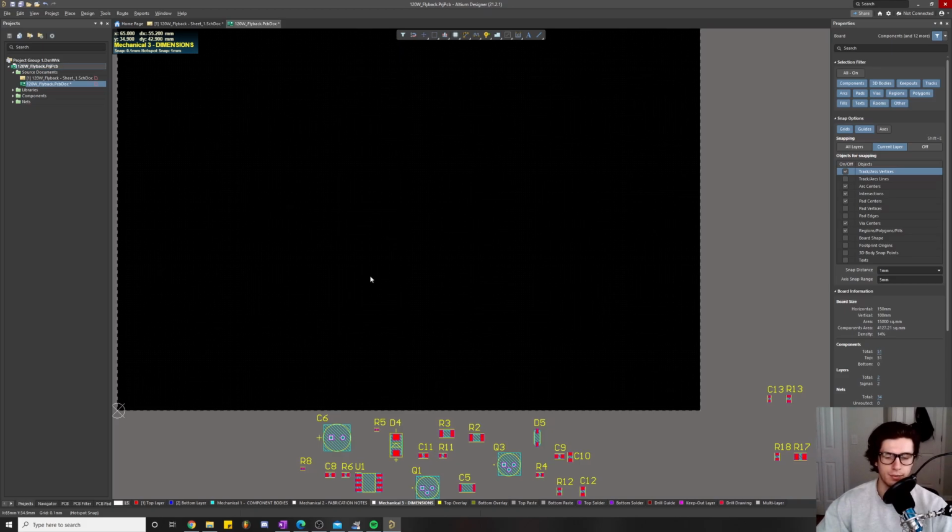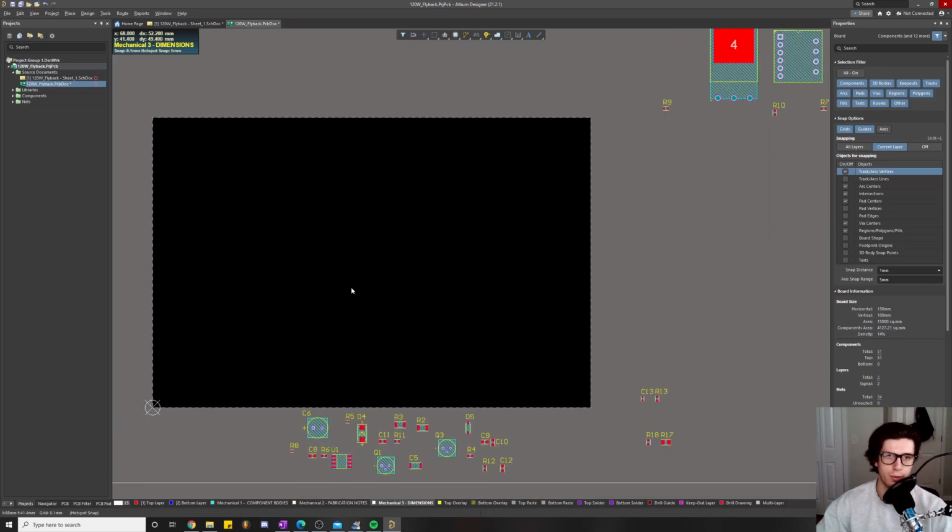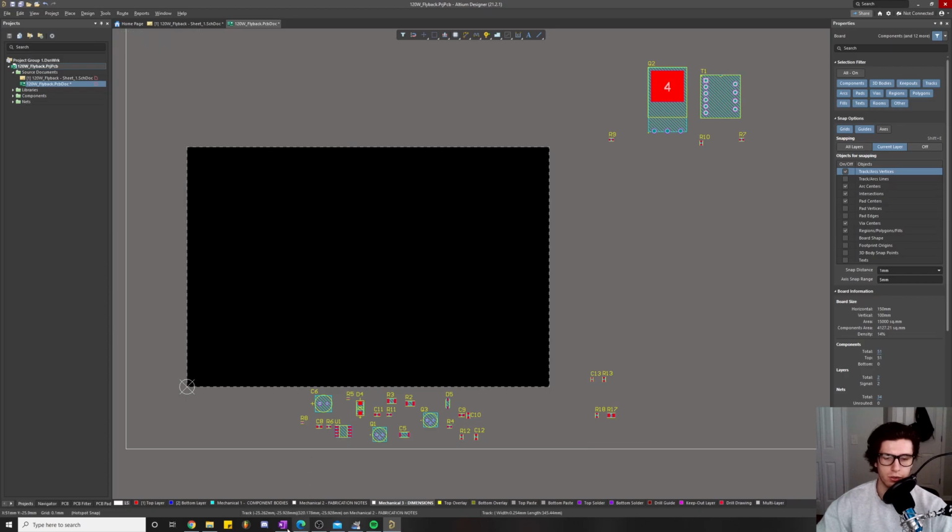And then also actual board performance. You could be warping the board, and you could be reducing the longevity of components by doing this. So be very aware of what components get hot, so you can appropriately space them, maybe place them on different sides of the board so the board can act as a heat sink, stuff like that. I'll show you exactly how I do it whenever we do the actual layout.